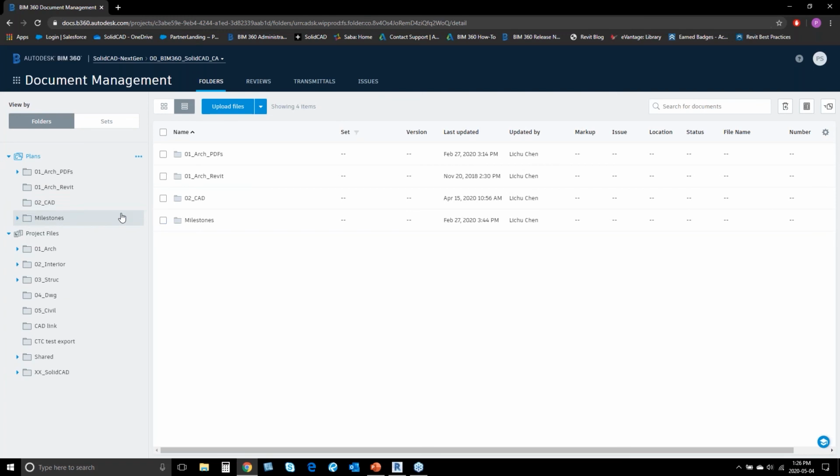Also within the BIM 360 area, you are able to create folders simply by clicking the dialog box and adding subfolders. With those subfolders that have been created, permissions are then granted to each user depending on which folder you want to give access to. Permissions are based off of viewing, editing, uploading, or downloading.